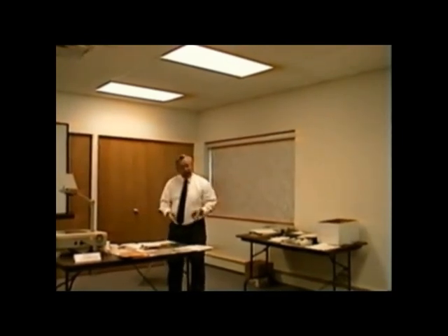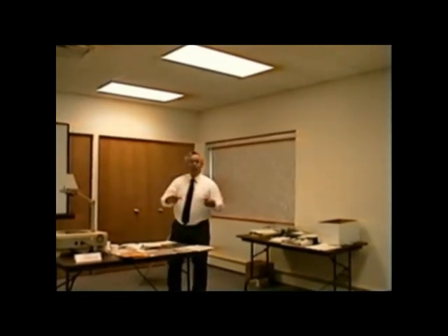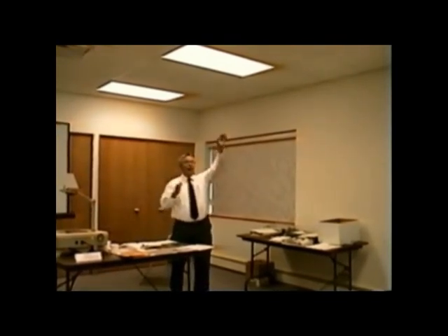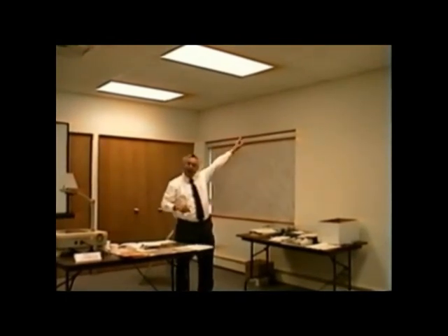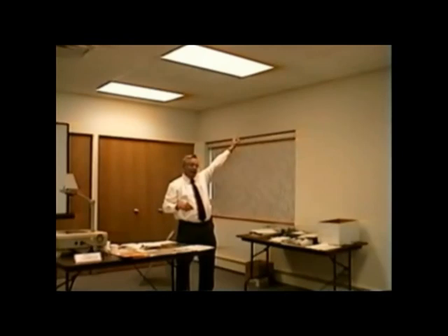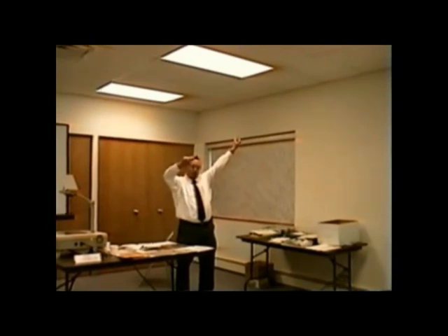On the supply, ladies and gentlemen, if you talk to several people, you're going to get several different opinions. We're going to suggest in this class that you take the probe for your supply. Here's your plenum. Let's say it's an upflow. We're going to ask you to go about 5 or 8 feet down the plenum before you put that probe in there. We want an average of that supply temperature. Now, other people that you talk to will say, well, no, you can come right over here above the A coil.